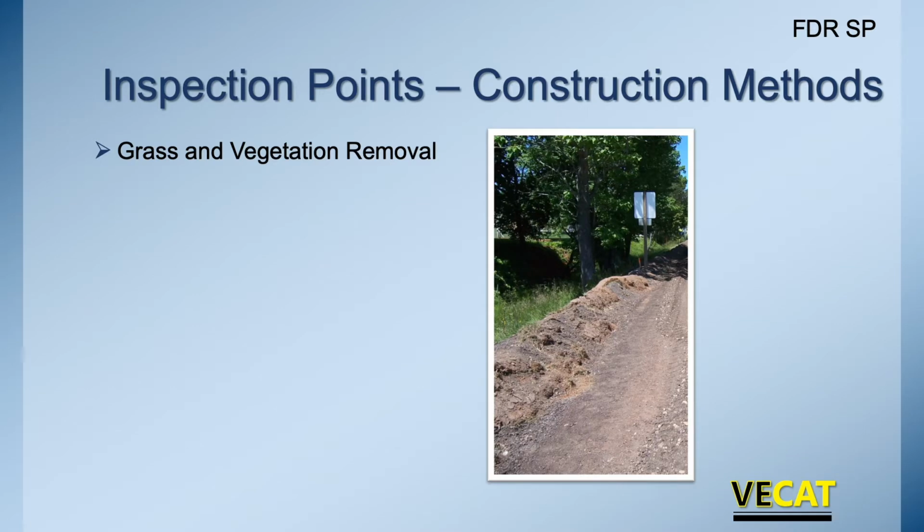Once we get started, we've got to make sure the grass and the vegetation is not being reclaimed into the mainline, because we don't want to have those organic materials mixed in with the new pavement structure.